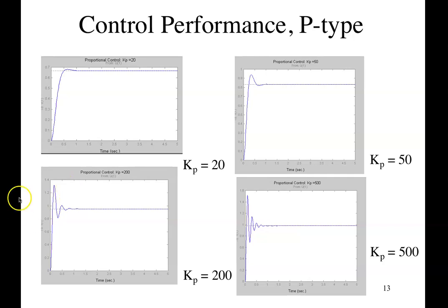Overshoot is a lot bigger. So this is around 1.3 compared with 0.95, so it's more than 30% of overshoot. And it goes up and down quite a bit and then settles down. So it doesn't really change the settling time that much. Perhaps it's actually a little bit worse.